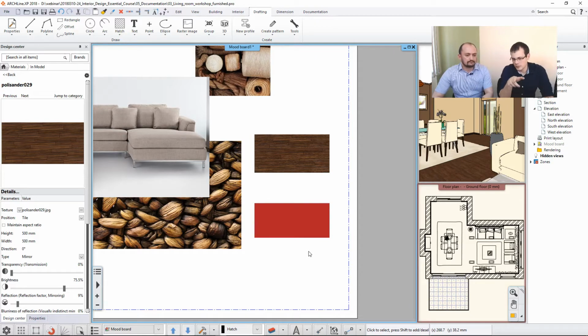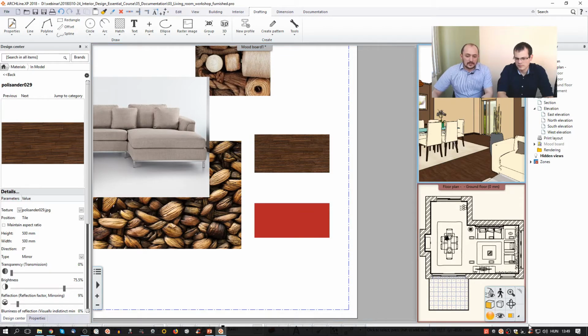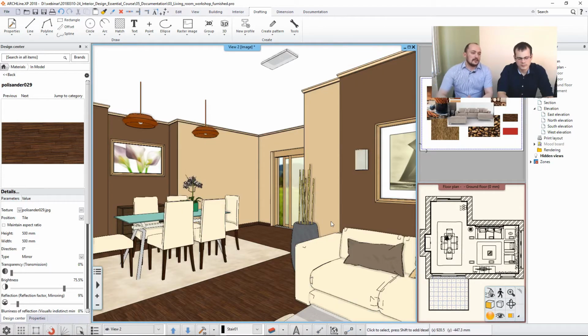You said that you're not able to bring in any three-dimensional data onto the mood board because this is a 2D documentation. Yeah. What happens if I want to document somehow my 3D model and include that in this mood board? That's actually not that much difficult. You just zoom in to your 3D model, the perspective that you already have. If you want, you can rebuild the 3D model. We already covered that, how you can refresh the 3D content when something changes. And then you just need to take a photograph, a snapshot, we call it, of this image.